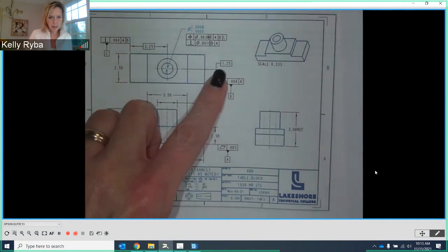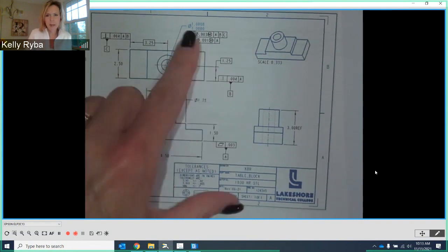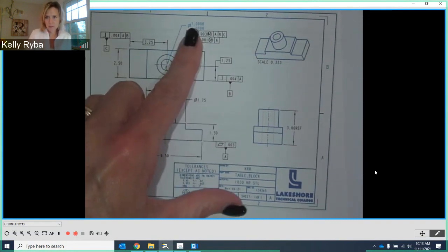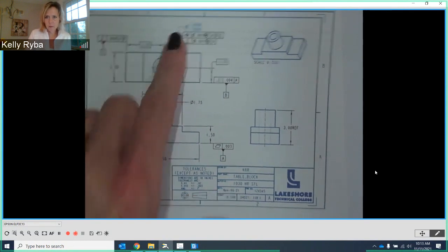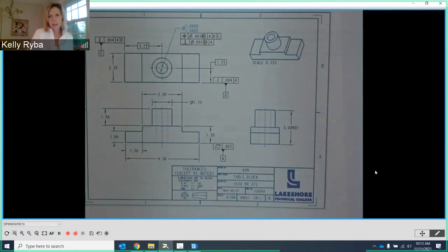after. So let's go back to Creo over here. Let's work on that top view first. Select that. I'm going to go into the show annotations and then kind of put all these here. Now, instead of trying to figure out which dimension it is over here, what I'm going to do is just select the ones that I know that I need. I need the 2.5, and it's going to go black for me, and it'll automatically check over here. So that's good. I need the 1 inch dimension here. That's going to be my hole diameter.